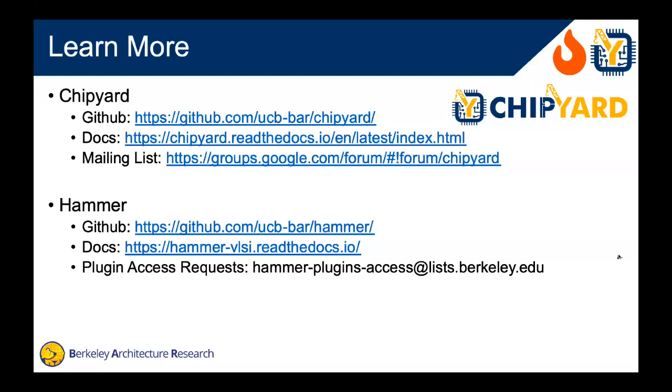You might exclude them. There's certain extra commands you might need to run to clean up dangling whatever's, right? These kinds of things take time, but it's hard for me to estimate exactly how long it takes for us, but we've gotten several plugins to this level of maturity where you get a DRC clean design out first. And I assume when you mentioned architecture convergence, you're probably referring to the feedback annotations.